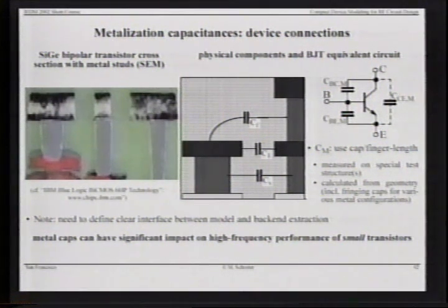And I've tried to visualize this a little bit better here with the different capacitances that would have to be calculated. And then we have to add these capacitances to the typical available compact models in simulators, and especially at small transistors, or sometimes also depending on the layouts for power amplifiers, these capacitances can be very important and degrade